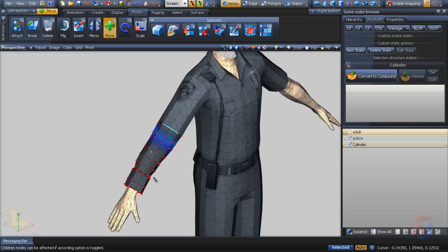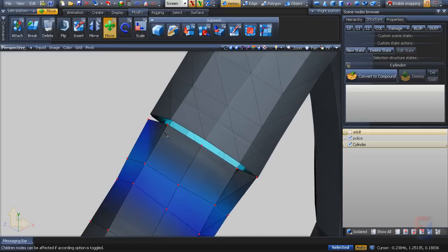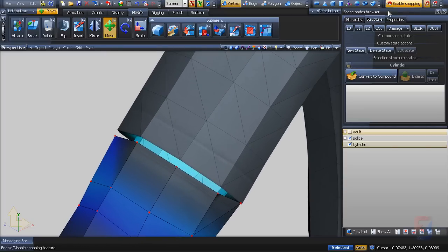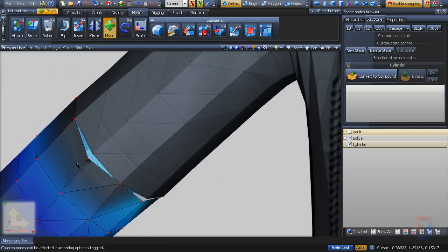Deselect. I use the Modify, Move tool and toggle snapping on. Toggling snap to vertices is a must too. You can leave snap to vertices on, and toggle just snapping on, off, when needed. I start dragging a vertex, and it snaps to a vertex of original model. Thus, I connect sleeve to the model with no gaps between.